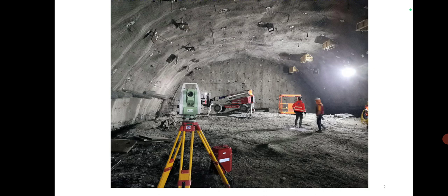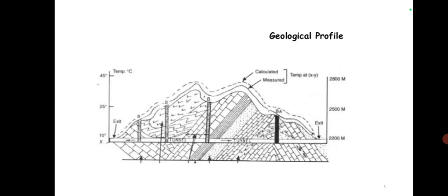We collect rock samples, and these samples are tested in the laboratory for their mineralogical composition, compressive strength values, modulus of elasticity, porosity, permeability, resistance to weathering, and chemical characteristics. All these are determined.